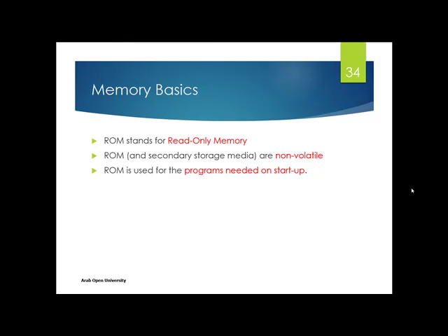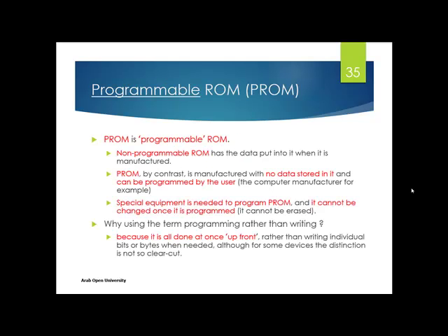So let's move to the evolution of the read-only memory, with the programmable read-only memory, or the PROM. PROM is programmable, which means that when it is manufactured, there is no data stored. It can be programmed by the user, but once it is stored, it cannot be changed. We use the term programming rather than writing because it is done upfront before using it, while the term writing is related to changes that can be done after starting to use the memory.